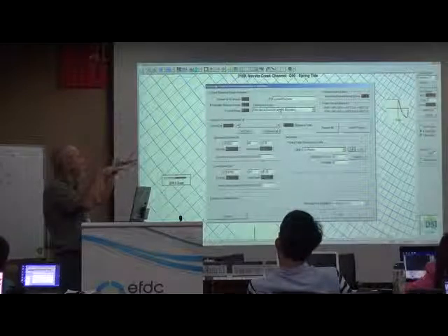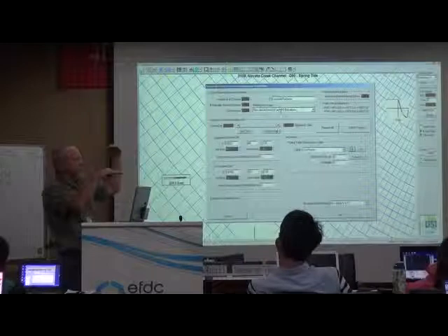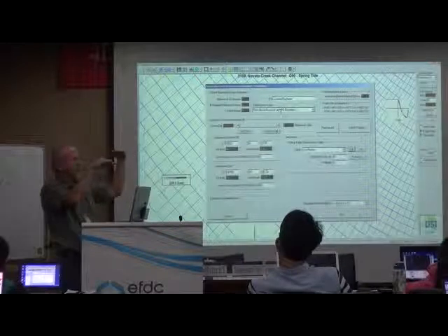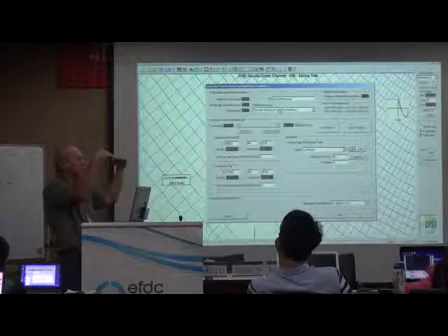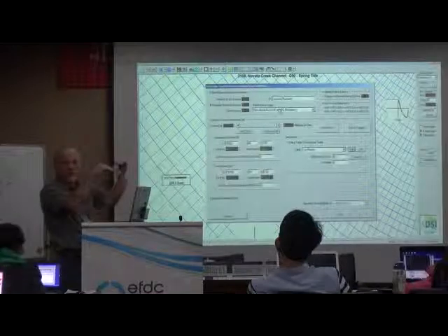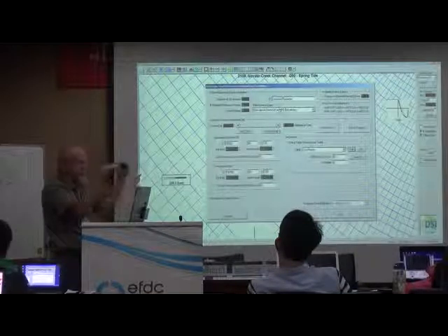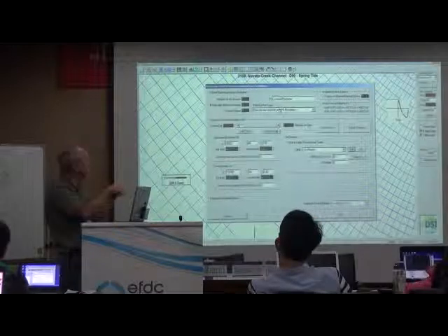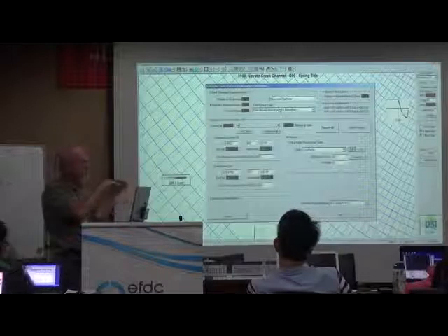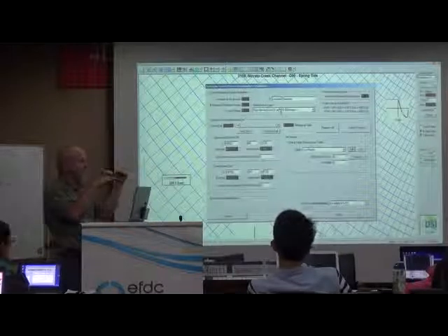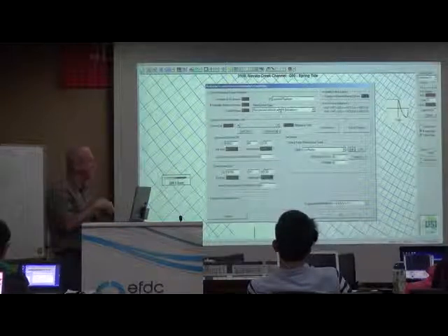I know my flow based on the rating curve and a given upstream head, and as the downstream head increases, it begins to submerge the hydraulic structure, and your flows will decrease as your head increases. And those tables can now be put into EFDC and the EFDC Explorer, and you can visualize it and manage it more effectively now.